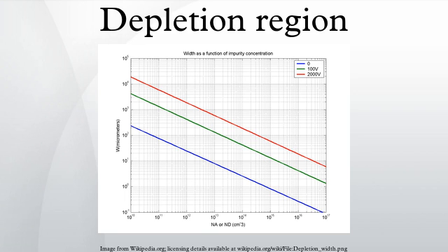The following discussion is limited to the P-N junction and MOS capacitor, but depletion regions arise in all the devices mentioned above. Formation of depletion region in a P-N junction. A depletion region forms instantaneously across a P-N junction. It is most easily described when the junction is in thermal equilibrium or in a steady state. In both of these cases the properties of the system do not vary in time. They have been called dynamic equilibrium.